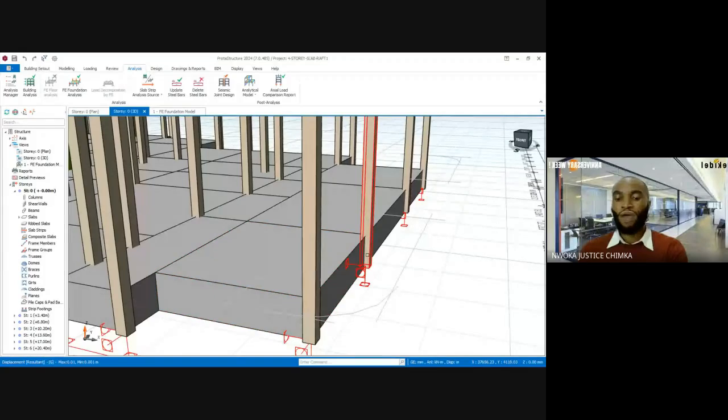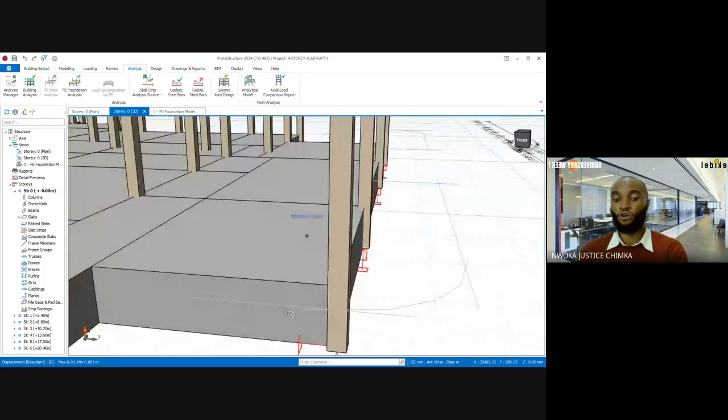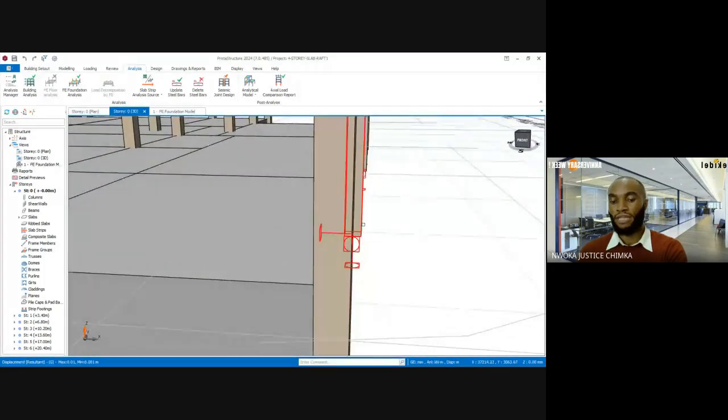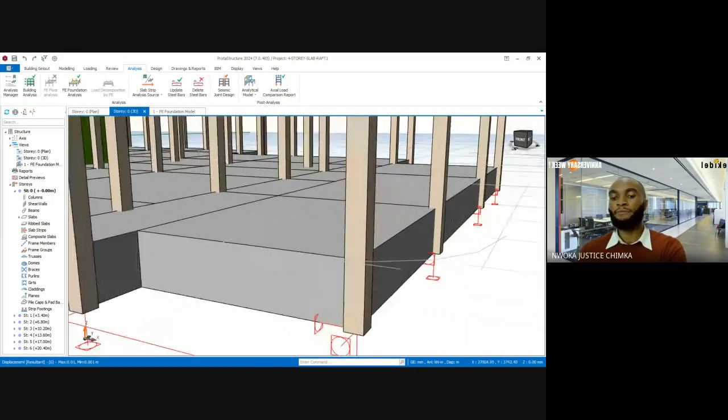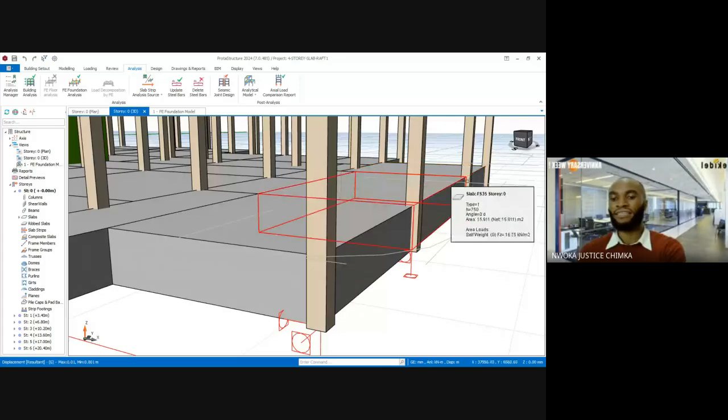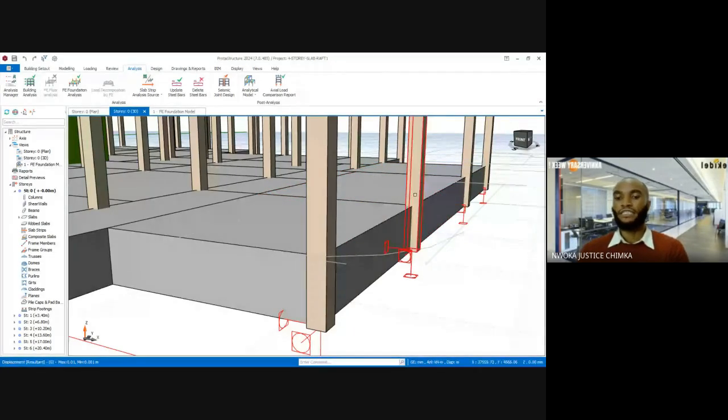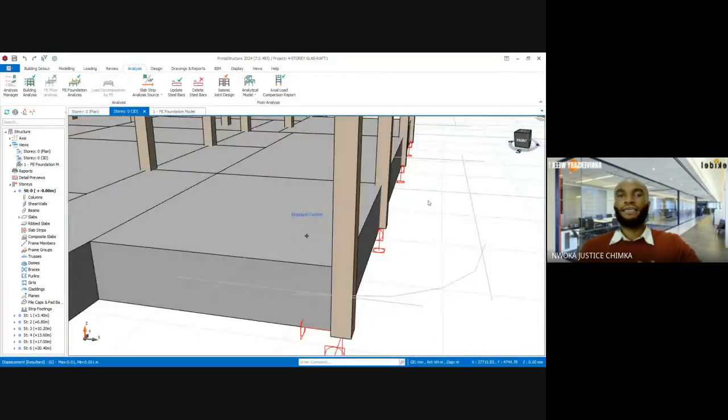The reason we are having that purple is because of the pressure. Since there is no slab around the column, around the perimeter here, the load on the column is hitting directly on this slab a lot. But had we extended this slab by at least 300, that load would have had a counterbalance, to be able to spread very well.